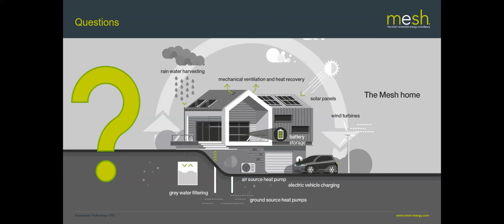Quite commonly with Tesla, for example, if you've got a 3-phase installation, one of the options, and it's only one of the options, is to put a battery on each phase, which means that they're 13.5 kilowatt-hours each. So that's again round about the 40 kilowatt-hour mark. So yeah, loads of choice from really quite small up to absolutely ginormous.